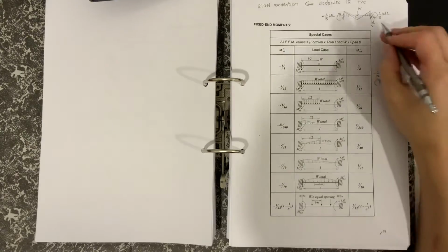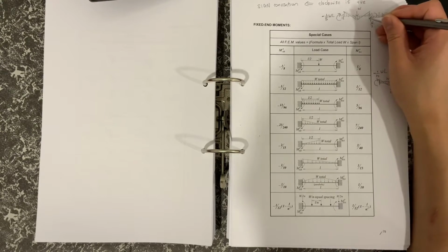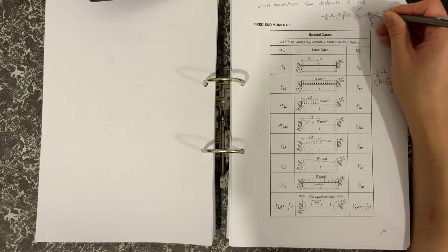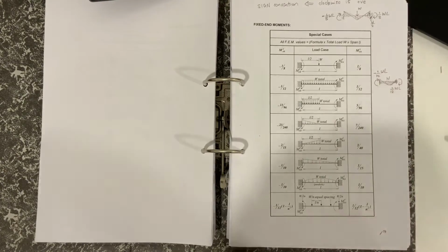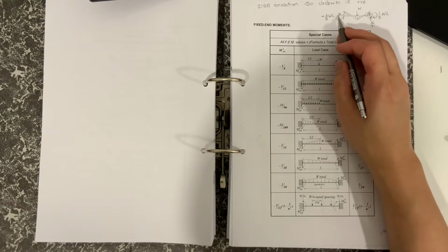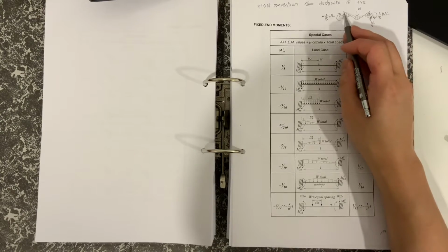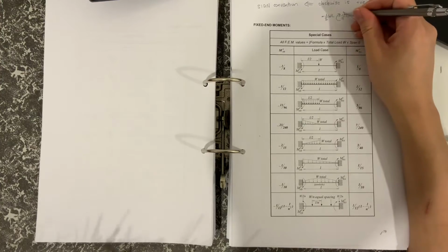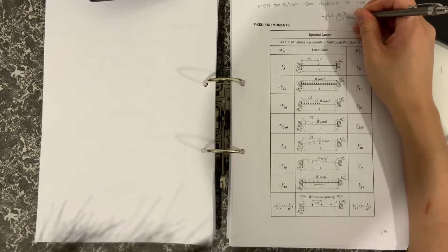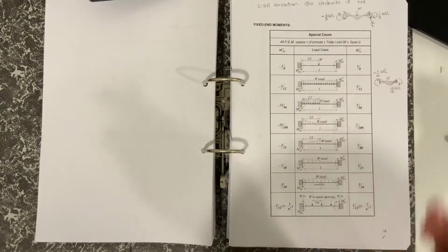And then let's look at this side here. Remember, the bending moment at that point would be acting in that direction, which would be in the same direction here. But this one, we know that it would be acting in that direction, but we've got to show the arrow as clockwise positive. So I would show it also in the clockwise direction, and then we know that we'll be using the negative sign.